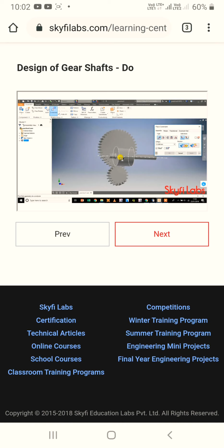In addition to these, we can also set motion and transitional constraints. As we want to align the axis of the shaft with the axis of the spur gear, we will use the Mate option. When we click on the Mate option, it asks for two selections. Selection 1 is first highlighted, to enable us to select the first feature. The first feature, in our case, is the axis of the shaft. So, make the first selection by hovering on the shaft and selecting the axis.